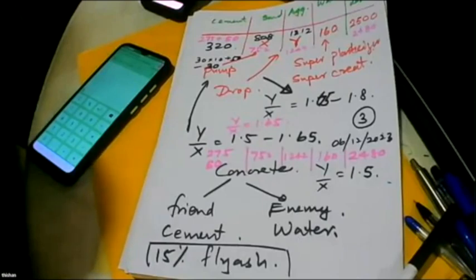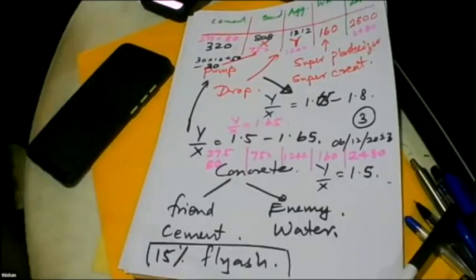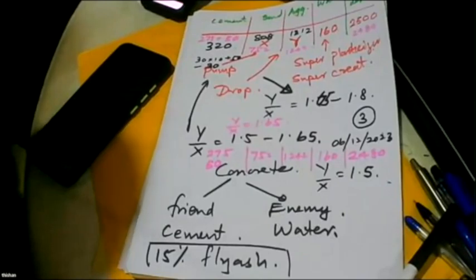No. Whether it is 30 megapascal or 40 megapascal is important only when you are designing as a beam. Even as a beam, you have a 3 meter thick raft. Would it matter? No, it won't.